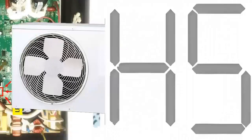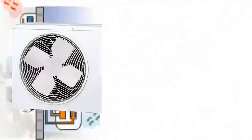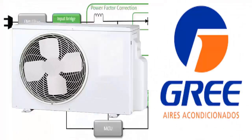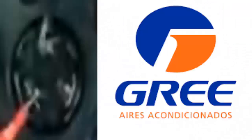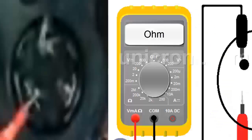5. Additionally, problems with the outdoor unit fan or lack of cleaning of the outdoor unit heat exchanger can cause system overpressure and excessive current consumption. Check the fan and clean it if necessary. 6. Electrical problems with the compressor can cause overcurrent consumption. Disconnect the compressor and, using a multimeter on the ohm scale, measure the electrical resistance between the pairs of pins on the compressor connector. All obtained values should be equal and should never read infinity.